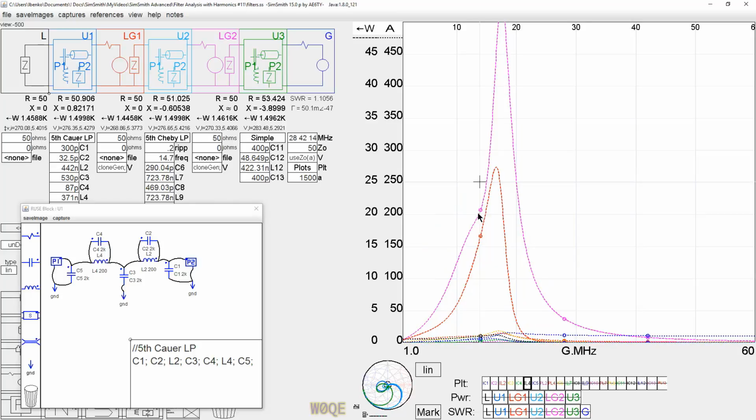Make those go away. So what we see is 20 watts is in one of the inductors. That would be L2, and L4 has 16.6 watts. 20 and 16.37, something like 37 watts here. And the 37 watts that we have here is basically what we saw when we did the load before, 1.46 kilowatts. I said it was 40 watts lost. This is 36 or 37 of them.